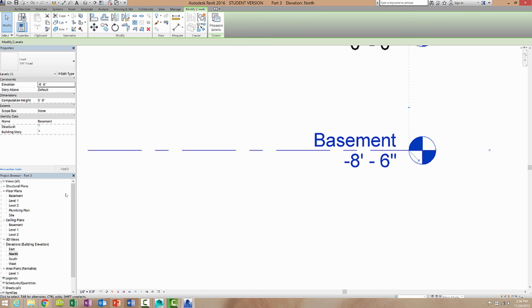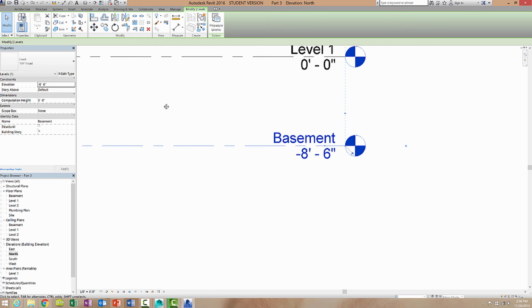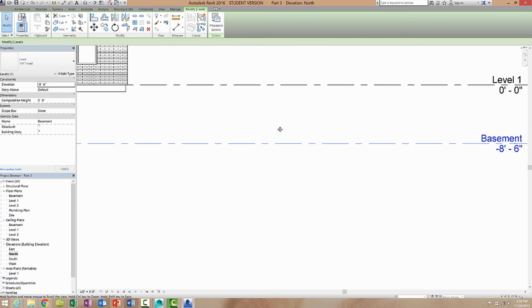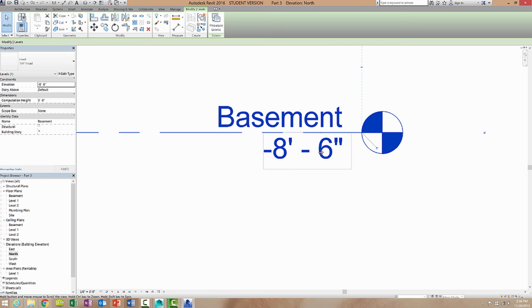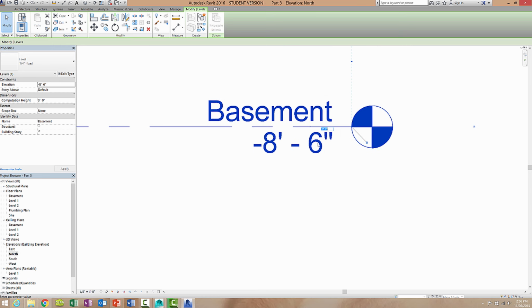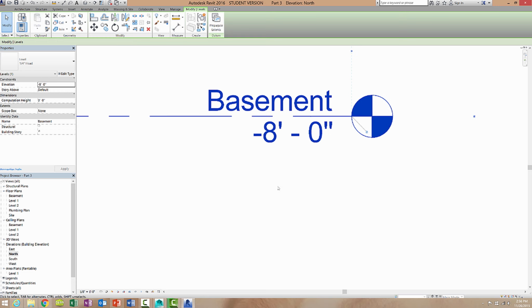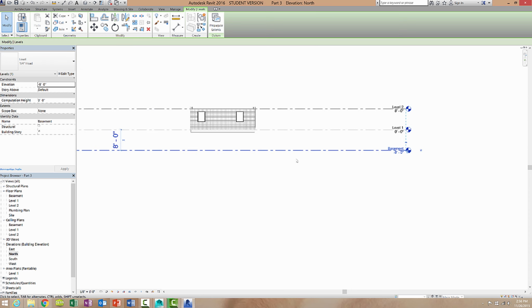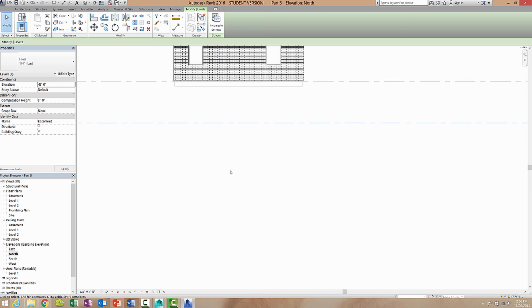I'm going to press yes, and now we have a basement for our floor plans as well as one for our ceiling plans. Now in the US, typical basements are around 8 feet. So we are going to adjust this to 8 feet, although if you wanted to leave it around that number, that is fine. Crawl spaces are around 4 feet or so.